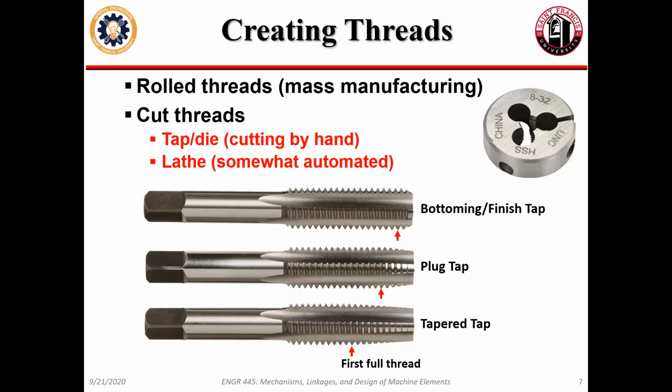Like you can get a 6-32 tap. It has the major diameter of a 6-32 screw and it has 32 threads per inch. You turn that into the material and it gradually cuts your threads. In order to use one of these, though, you need a hole that is a tap hole, or one that's drilled with a tap drill for your particular screw and thread size. It's screw and thread size because of the amount of stress you put on your tap when you're trying to cut threads.